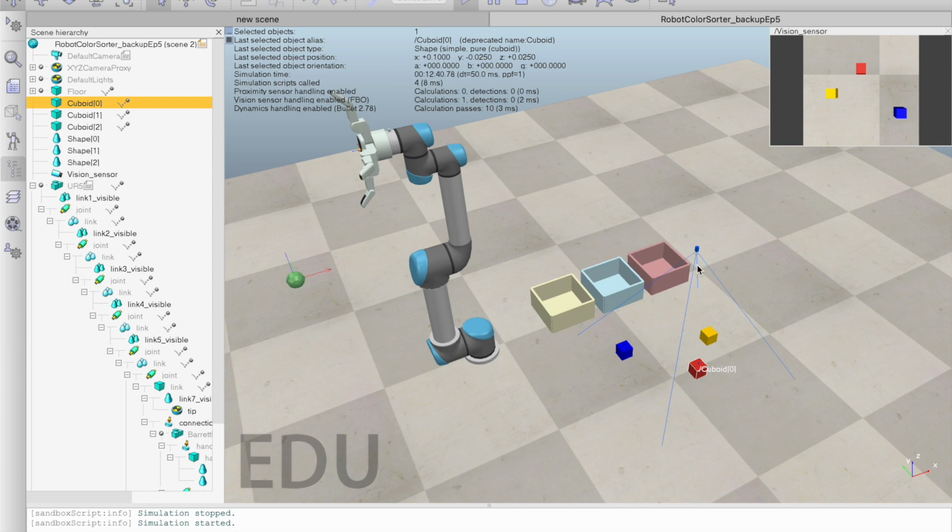So we're going to rely on anything that's fixed in this simulation, which means the camera, because that's part of the fixed setup that's controlled by the programmer or the user in real life. He places the camera in the position that he wants, so that means he knows where the position of the camera is, and the position of the robot as well, that's fixed. So what we're going to be doing first is getting the position of the camera with respect to the robot.